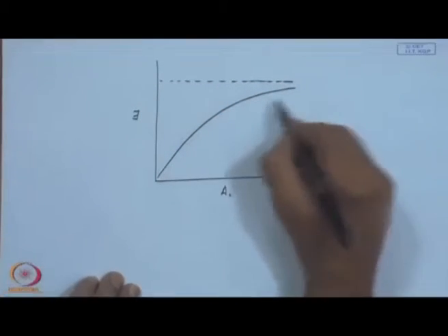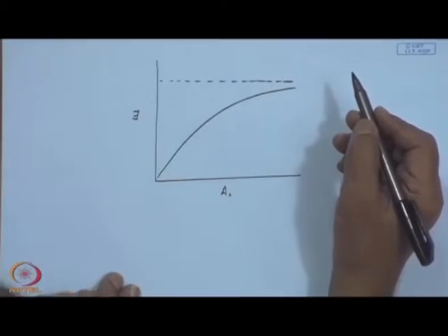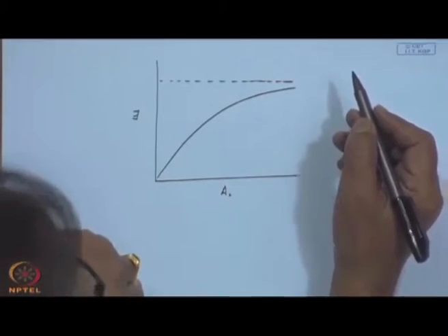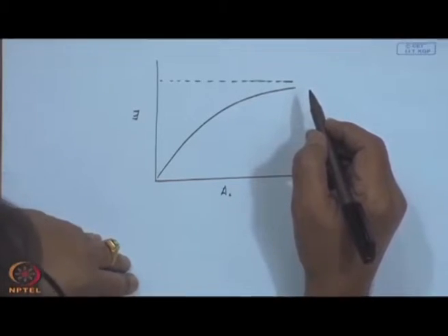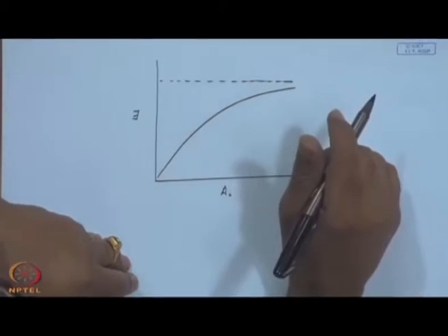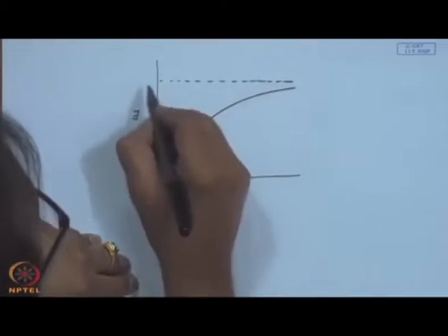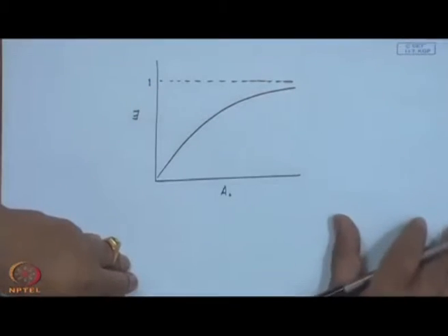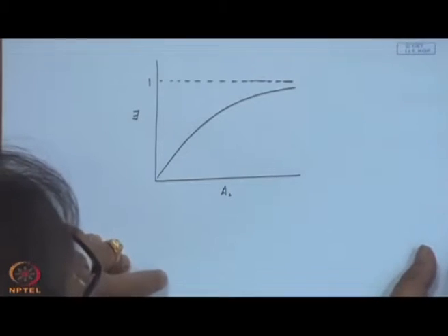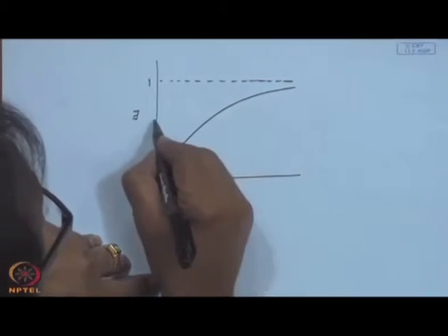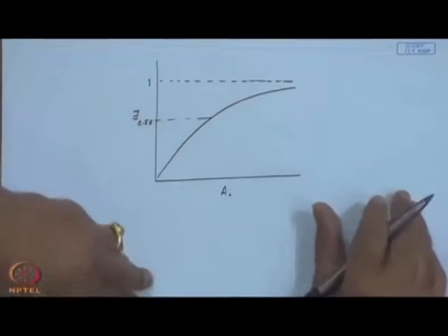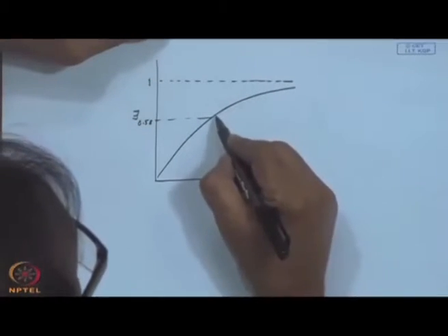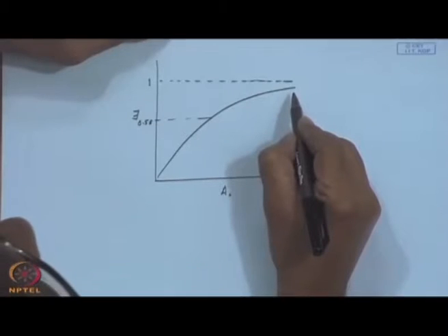Of course, this curve depends upon the type of the collector, performance, location, the parameters that you choose, etcetera. Given one set of curve, one would wonder whether you will go for a 100% solar load fraction or maybe something like 0.58. The reason is that it is increasing at a decreasing rate.